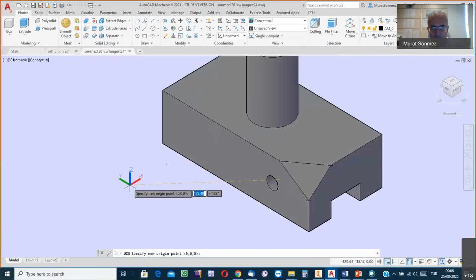So, thanks to this enabling, I can indicate this corner as the location for the origin of the coordinate system. Moving the cursor here, and after seeing the green square used for endpoints, click the mouse. It is the location for the origin.